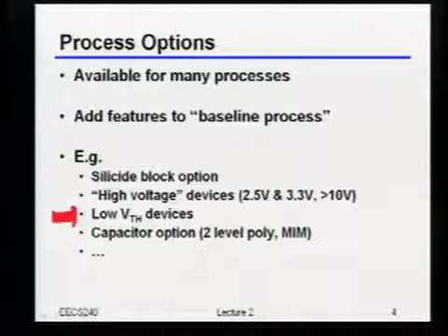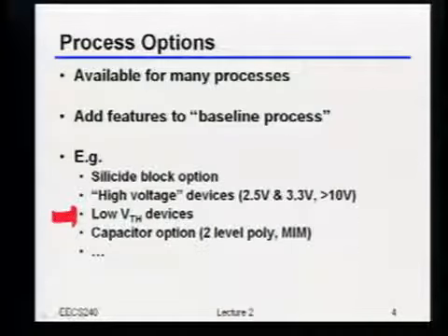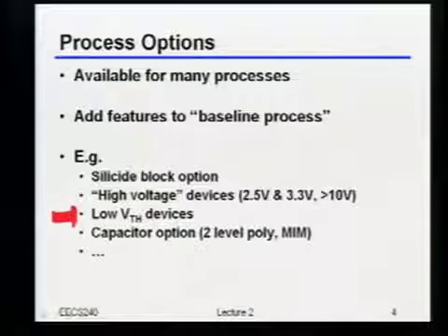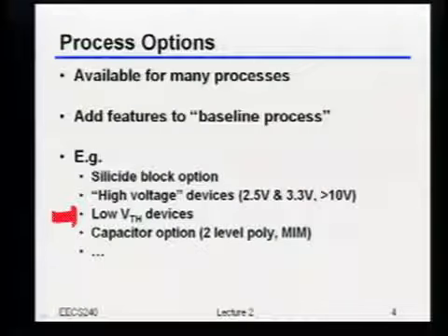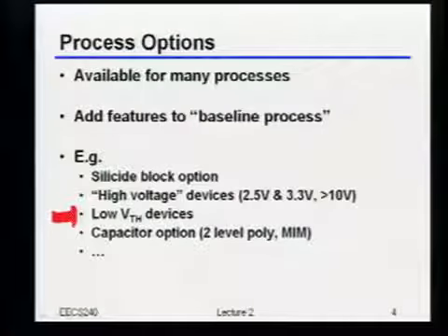So the guys who are in the fab, they're paying attention to the digital transistor. So if this low VTH device happens to just be there, they may not be paying too much attention to it. So from a practical standpoint, what oftentimes happens is even though you have this option, it's so poorly controlled that actually you don't know what you're really going to get. And so you're better off just sticking with something that you know what it is and designing around whatever issues that ends up causing, rather than having a bunch of just unknowns that potentially could screw you up and then make the thing not work.